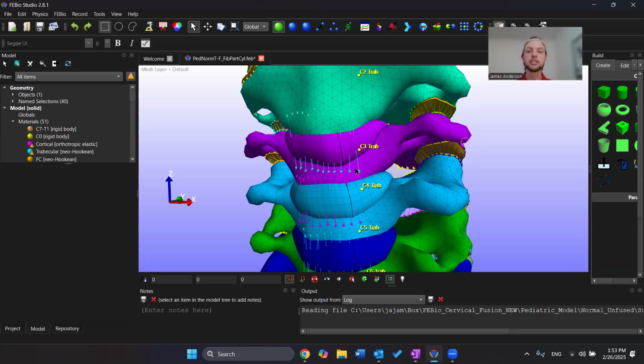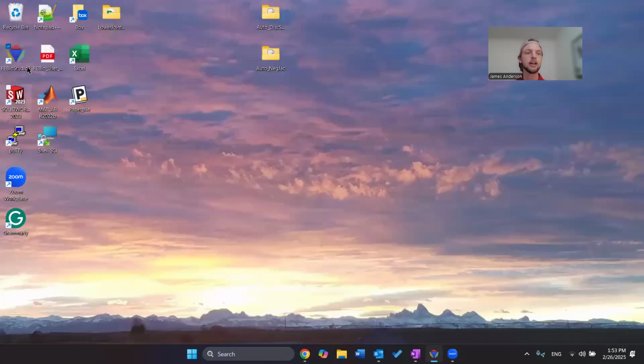The second reason is, for example, if you have two contact surfaces and they're complex, you may want to slowly bring them together before you do any crazy motions so that they don't accidentally go through each other because the computer doesn't patch them. These multi-step analyses can be a workaround to solve issues like that. With that, let's get started.